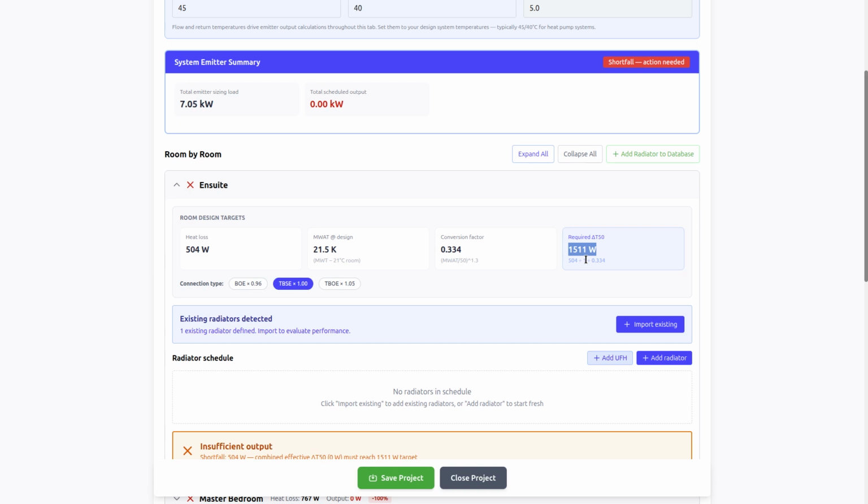Now, they don't have to have bigger radiators, they just have to have the right size radiator. In some houses, small radiators are fitted. In other houses, big radiators are fitted. So we have to figure out how much heat fitted radiators can give under the circumstances and conditions for an efficient heat pump installation. I hope that makes sense.